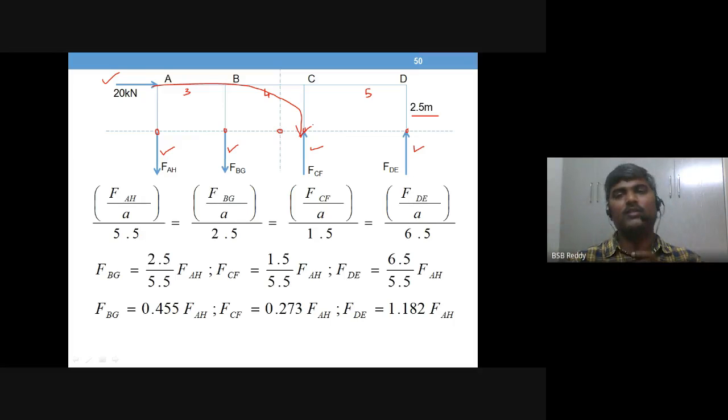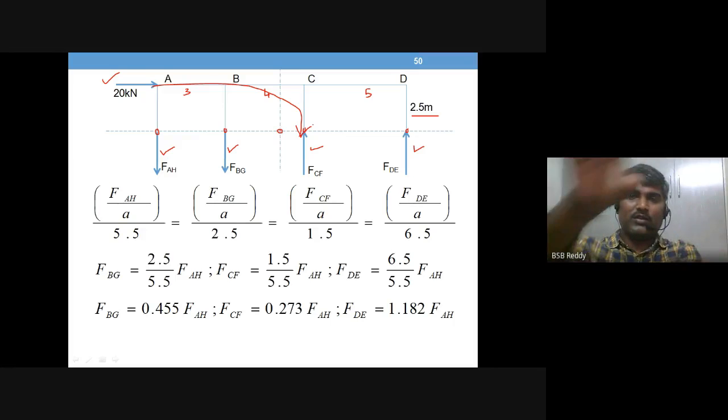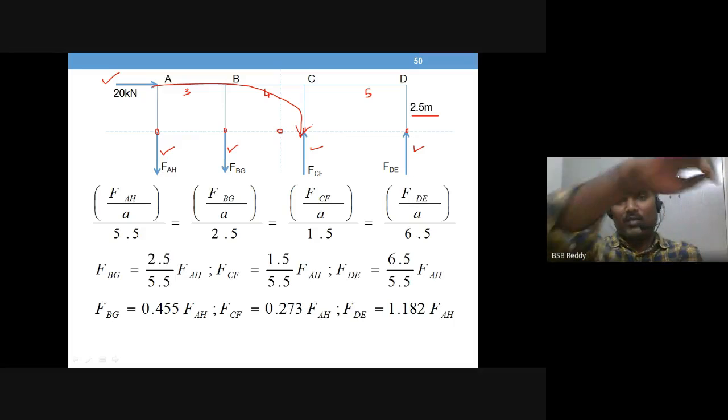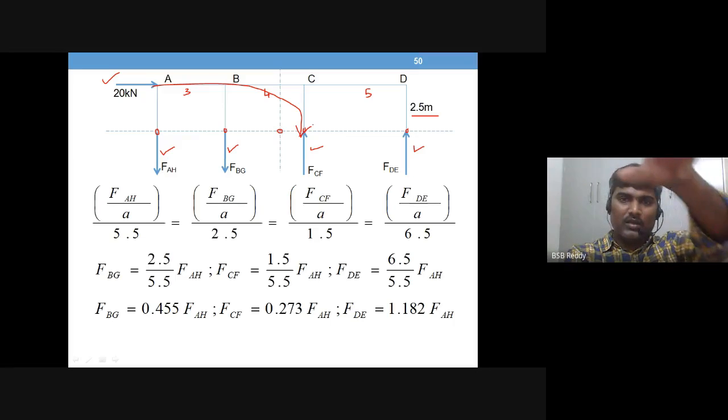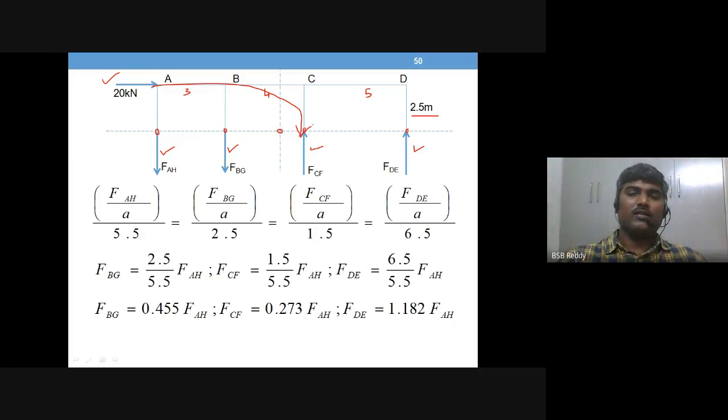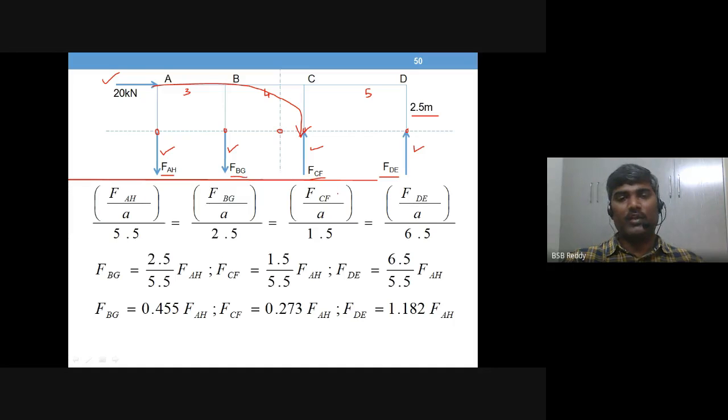That is what is being given. The same is the notation. So left columns downward forces, right columns upward forces. So these column axial loads will try to resist that bending moment applied. So applied is clockwise and reaction is anti-clockwise. Okay, so this is why the downward arrows and upward arrows. Okay, right. So this is the next step. Got it?